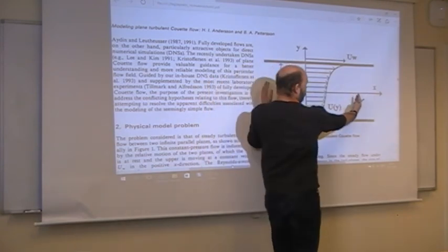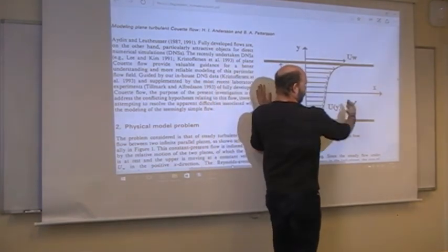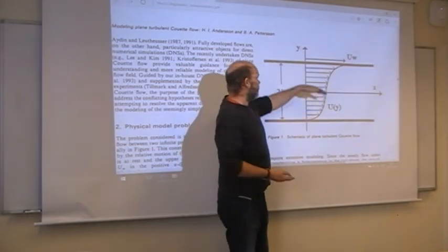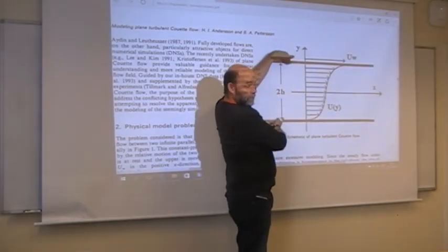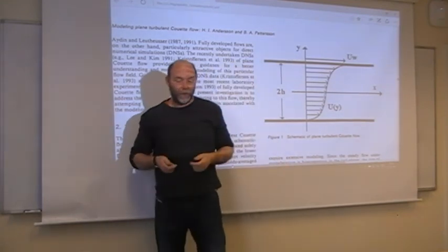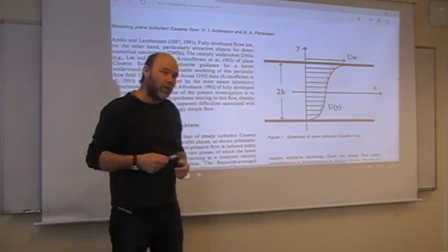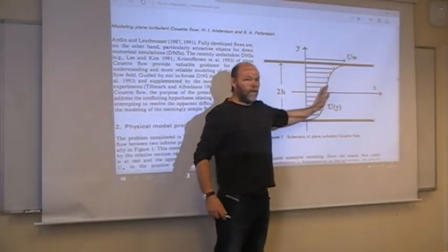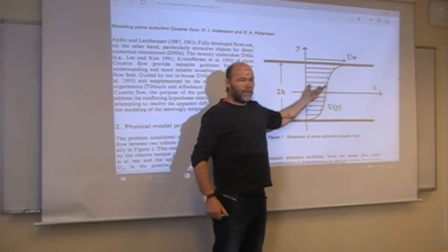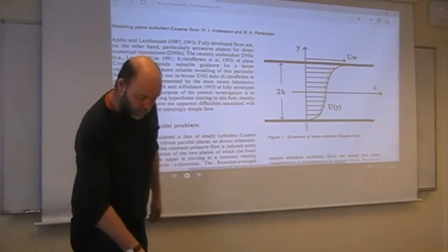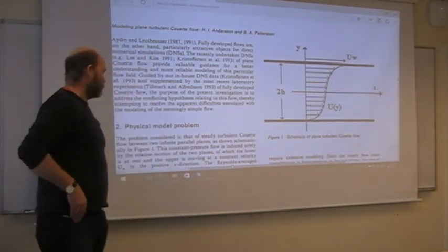You know the net pressure force acting on the entire fluid. That one has to balance the friction, the wall shear stress. So you can calculate the wall shear stress there before you begin. But then what you don't know is the velocity. What will the average velocity be? And what will the Reynolds number be? You don't know in a Poiseuille flow. So in a Couette flow, totally different.